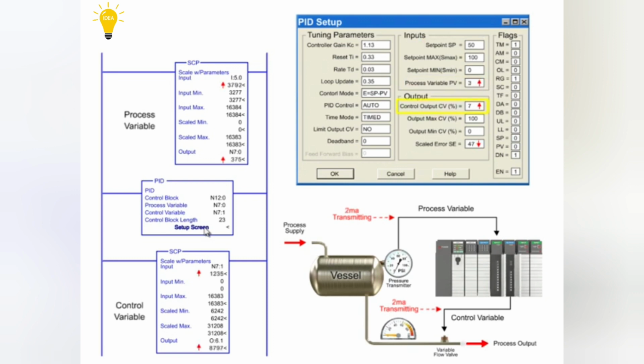By increasing the control output, the error is reduced to attain the set point as the psi is raised in the system. In other words, the valve position is gradually closed to reduce the pressure loss. Upon reaching the set point in the system, the control output and scaled error is reduced to 0.